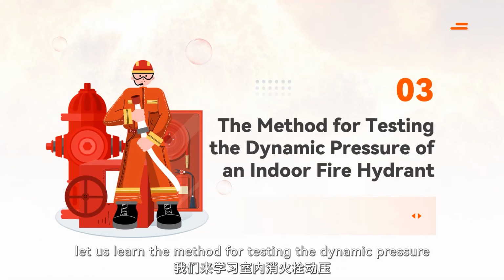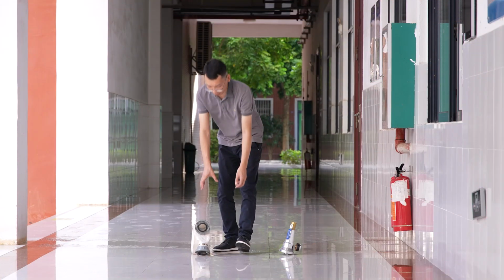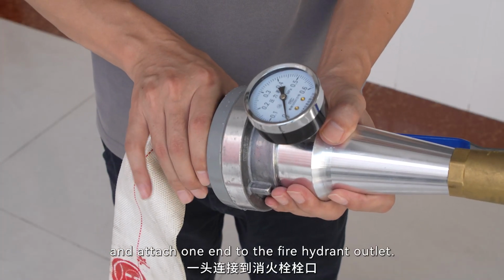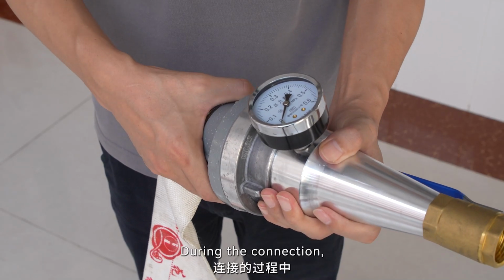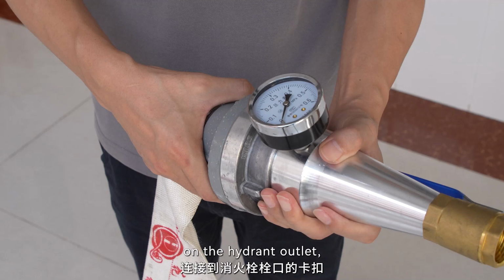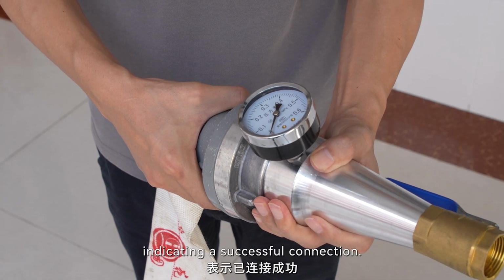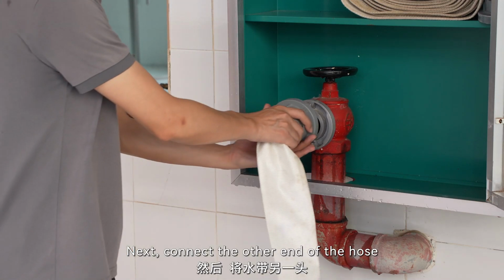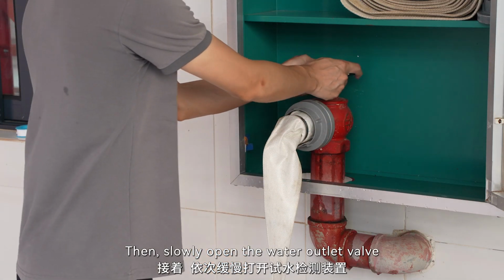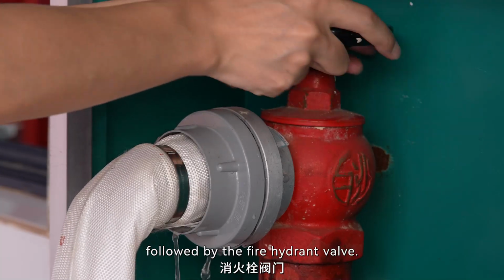Now, let us learn the method for testing the dynamic pressure of an indoor fire hydrant. First, connect the hose, unroll and straighten it, and attach one end to the fire hydrant outlet. During the connection, align the hose's clip with the corresponding clip on the hydrant outlet. Then twist in a clockwise direction until you hear a click, indicating a successful connection. Next, connect the other end of the hose to the inlet of the test inspection device. Then, slowly open the water outlet valve on the test inspection device, followed by the fire hydrant valve.